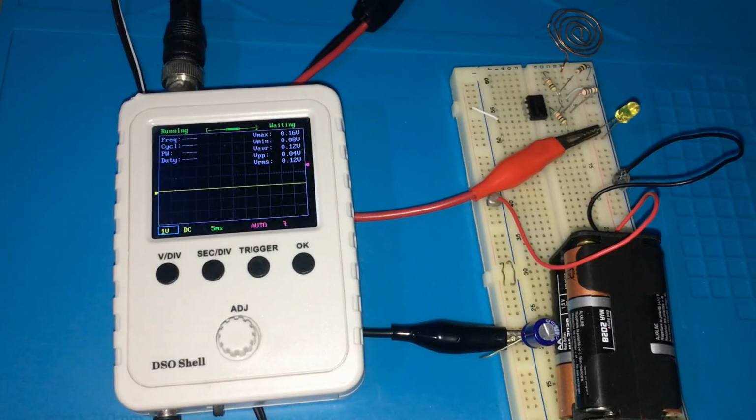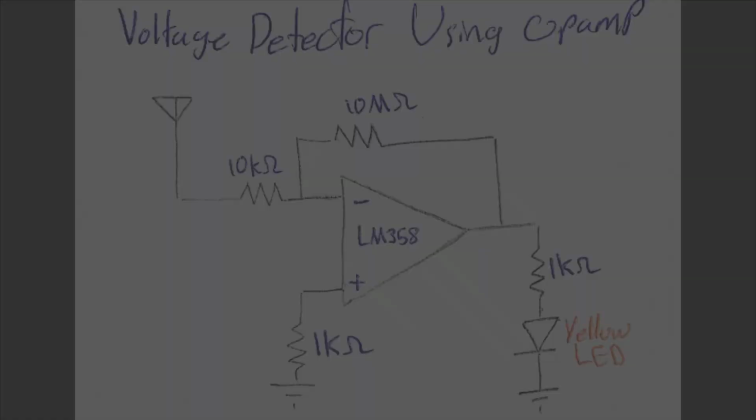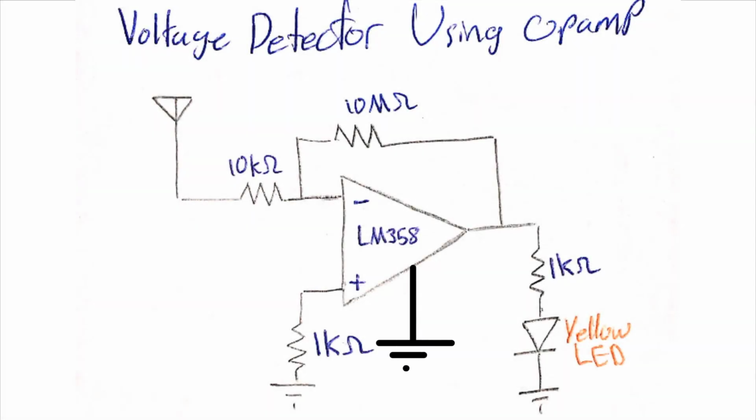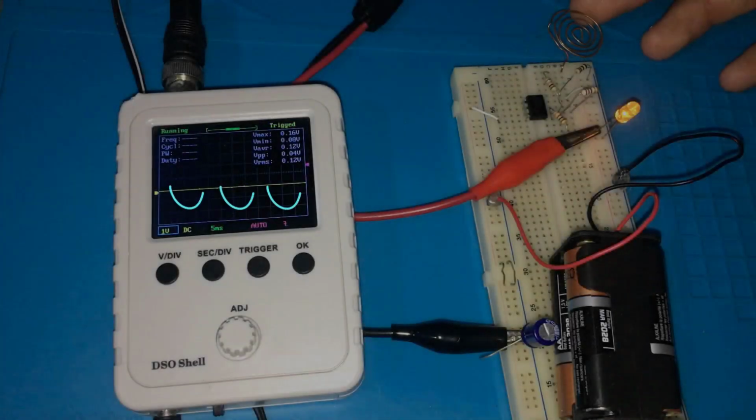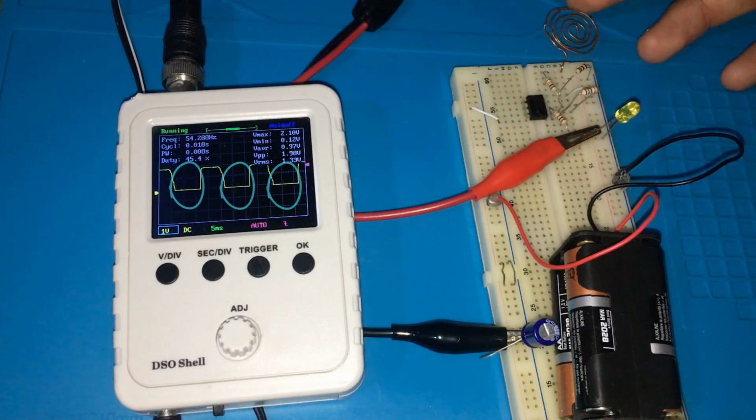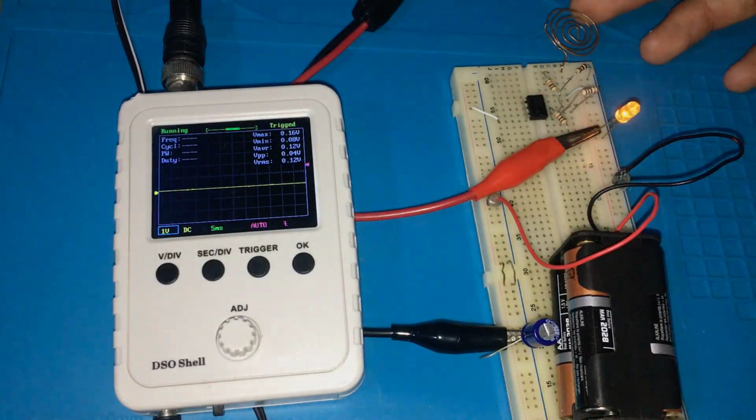I've built the circuit on a breadboard, tested its output using my oscilloscope, and it worked fine. As a note on the output signal, since the Opamp V- terminal is grounded, the signal is clipped at 0 volt. To make the comparison more clear, let's compare it with the input signal.